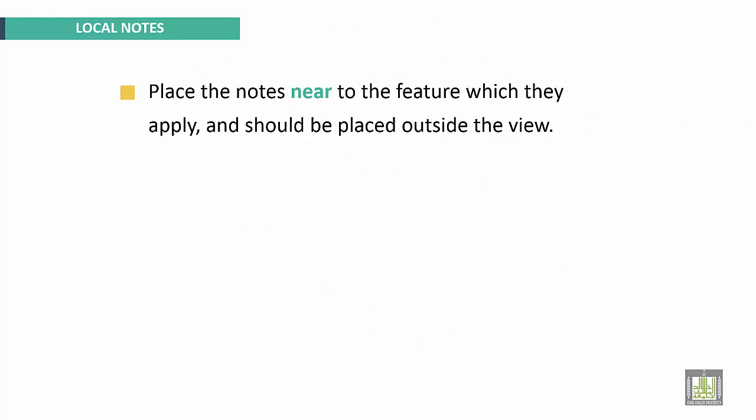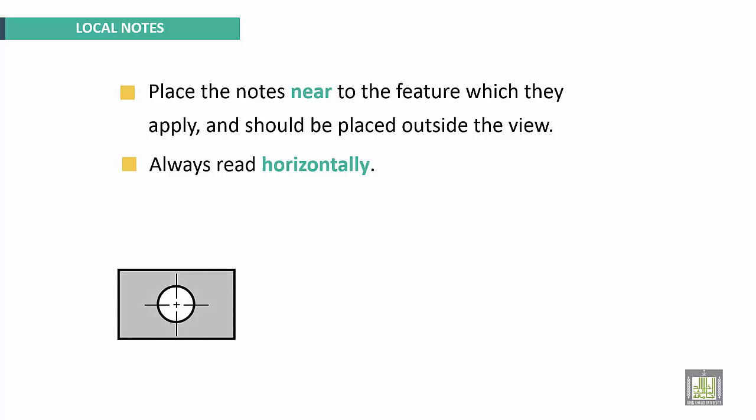Local notes. Place the notes near to the feature which they apply and should be placed outside the view. Always read it horizontally. One example here, this is local note 10 drill, and put here space of about 10 millimeters.